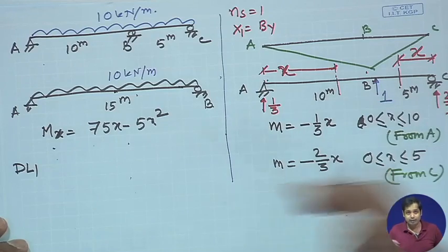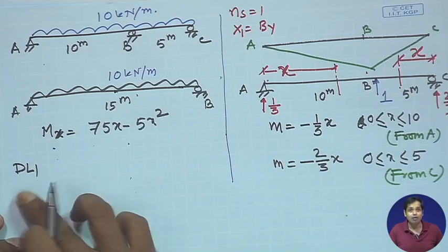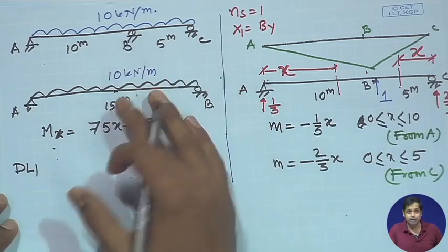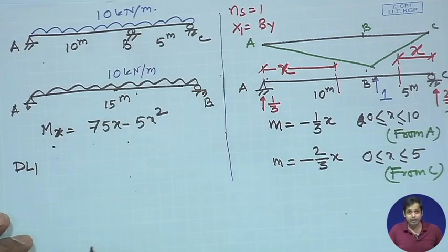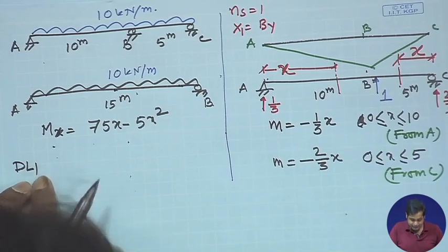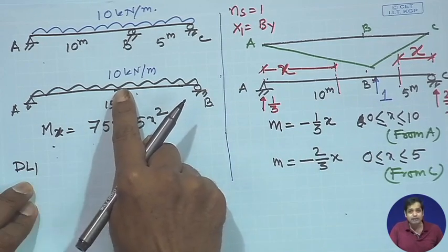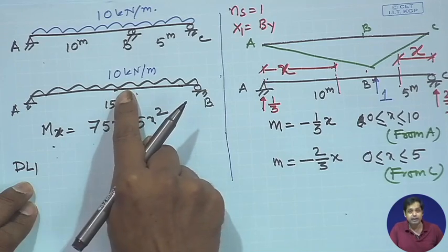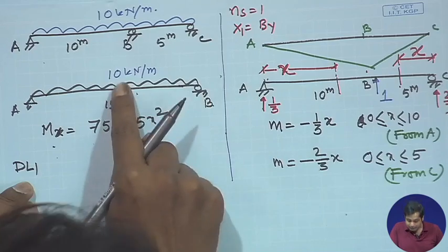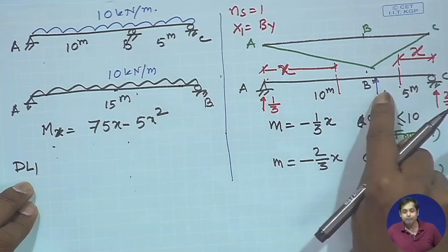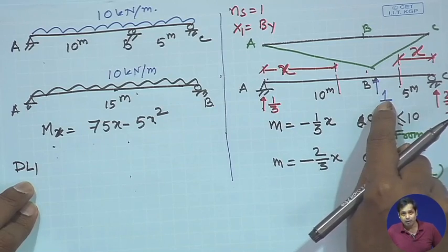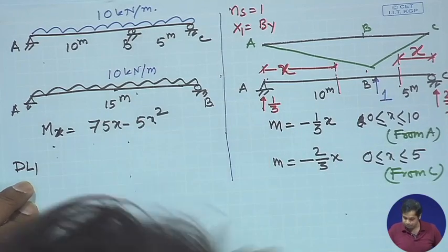If you recall, in the last week, this is how we denoted the associated displacement in the primary structure subjected to externally applied loading. So, dl1 is essentially the displacement in the primary structure due to the externally applied load, but that displacement in the direction of x1.